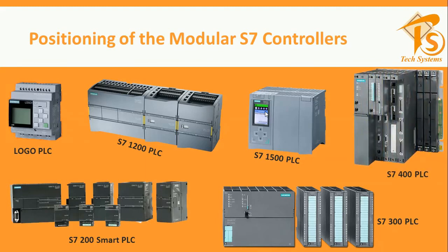And this is the boss of all the PLCs, the S7-400 PLC. We use this PLC specially in DCS applications, distributed control system applications. If you have designed your plant with a DCS system, in this case Siemens has only one option for the DCS controller, the S7-400 PLC, and all the other options are used as slaves, but your master DCS is S7-400. So this is the main PLC S7-400, next S7-300, and downgrade S7-1500, S7-200, S7-1200, and also Logo PLC.